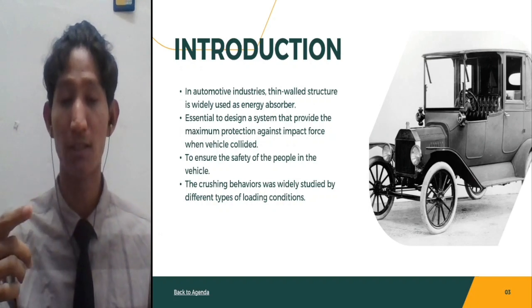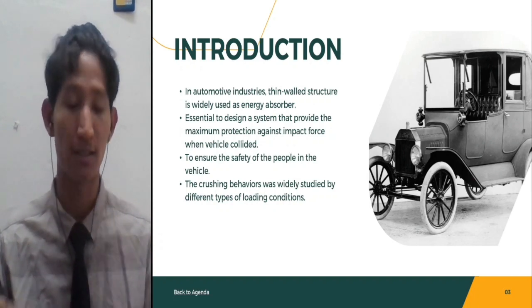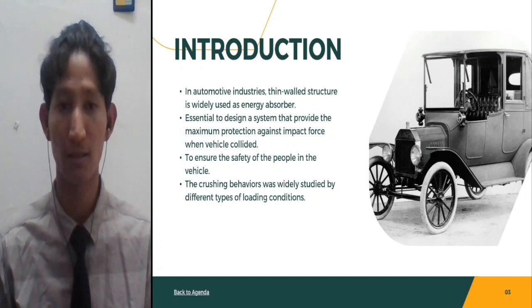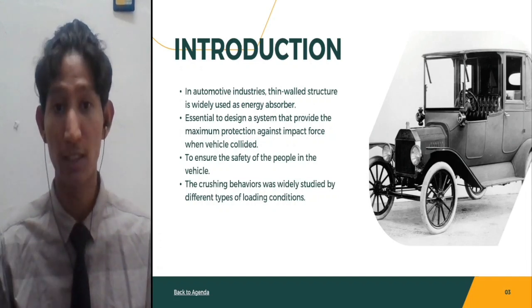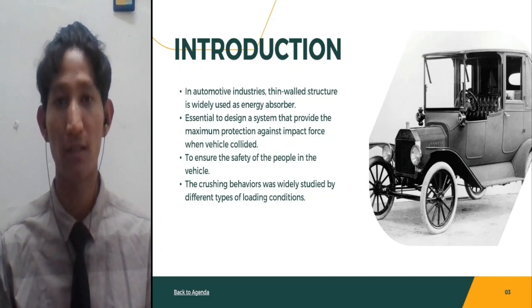The crushing behavior was widely studied under different types of loading condition such as dynamic, axial loading, bending loading, and also oblique loading, where they have an angle when crushing the tubes.